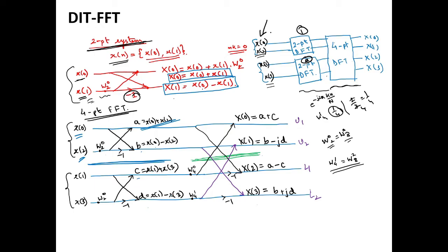Now over here, we have got this. Now what we have to do? We have to perform 4-point DFT. Okay. Now, once you are trying to perform the 4-point DFT, you are using all the 4 points. Again, you have to find out this midpoint over here. Why is this midpoint important? This midpoint is important because above this midpoint, the lines will have twiddle factor values of 1, and below it they will have the actual twiddle factor values. So over here we are performing 4-point DFT, so these lines contain W04. Why W04? Because we are performing 4-point DFT. The next twiddle factor is W14. Are you getting my point? W04, W14.